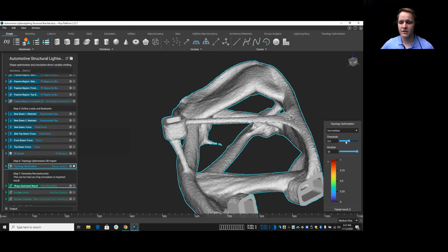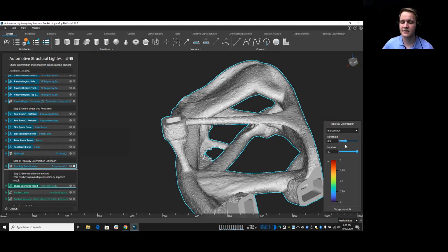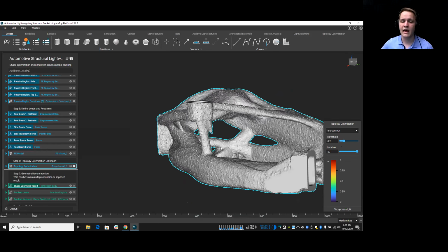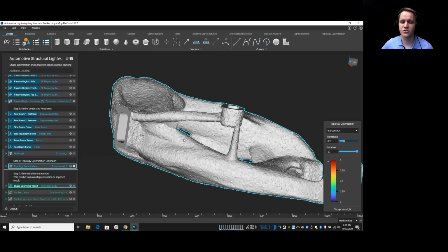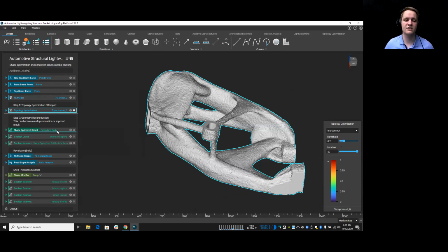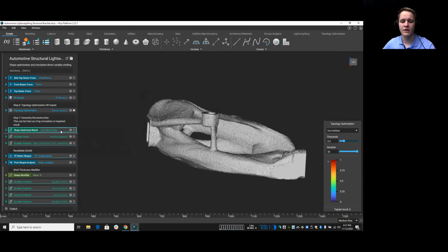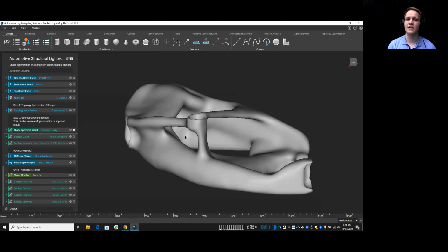nTop platform gives you a little bit more access. So if you want to bump up some elements that are maybe technically, according to the optimization, less necessary, you have total discrete control over this idea. So you can bump up that volume threshold, and now, we tackled the thin region area, now we need to tackle the surface. And in nTop platform, we have this block here called Smoothen Body. So to smooth this entire body into something usable, it takes about this much effort in nTop platform. You use one block and it's done.